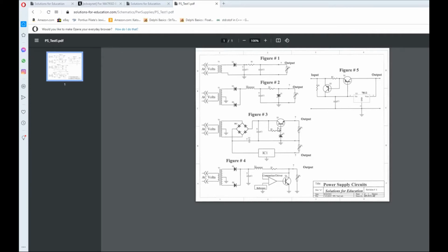And if you recognize it, this transistor is in the common collector configuration, otherwise known as an emitter follower. Now, what I'm saying is that whatever this voltage is here at the base, the emitter will follow it very, very faithfully, but about a half a volt behind, in fact, more technically about 0.6 of a volt. So therefore, if this is sitting here at 5.6 volts positive, then that means that the emitter will be a half a volt or 0.6 of a volt away from that, sitting here at right on the button of 5 volts.